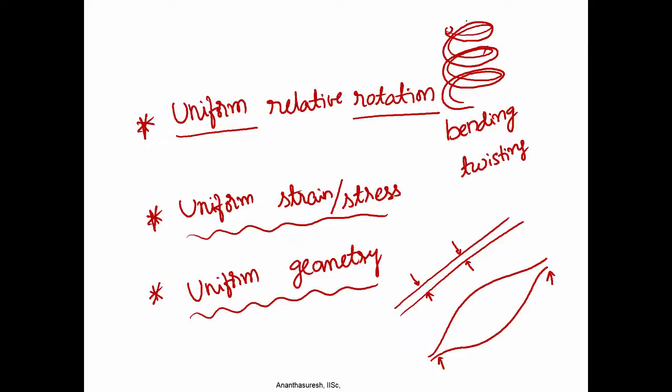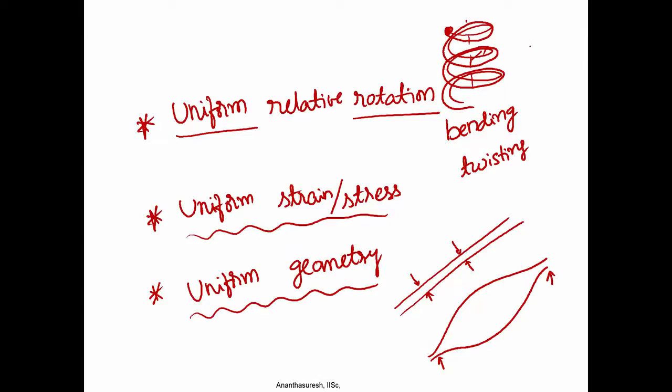Wherever you cut, as you would know from analysis of the beam spring, the same torsion is there at every joint, because the force times the radius. If the helix is a normal rectangular helix, we have the same torsion torque everywhere. So, you have the same strain and stress. Okay. Of course, not at the cross section, maybe the cross section as a whole. With the cross section, if you make it a helical compression spring with annular cross section, everywhere also it will have the same stress and strain. What about relative rotation?